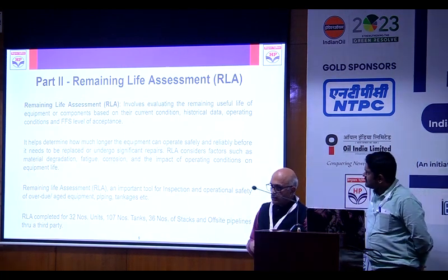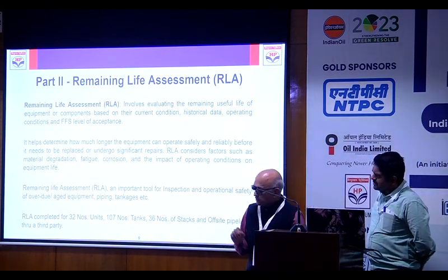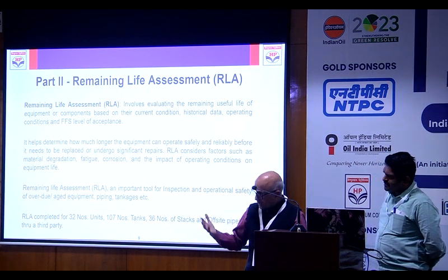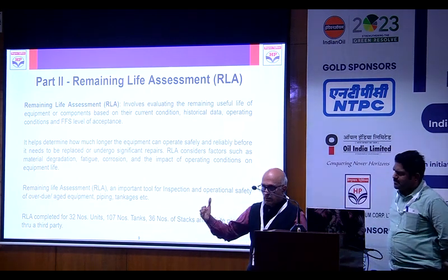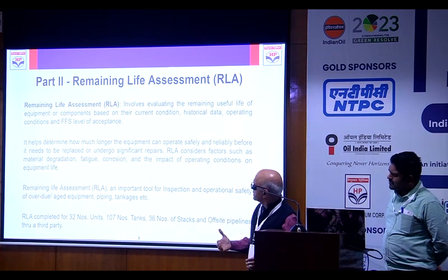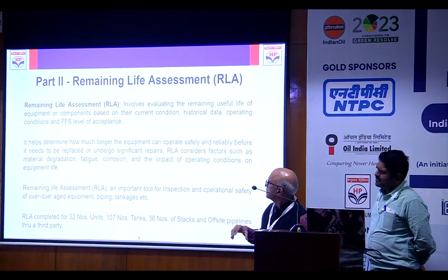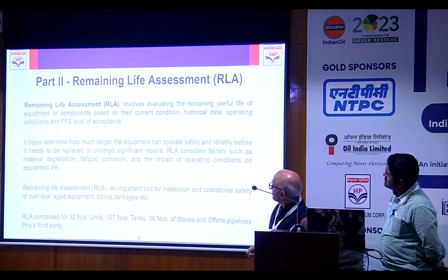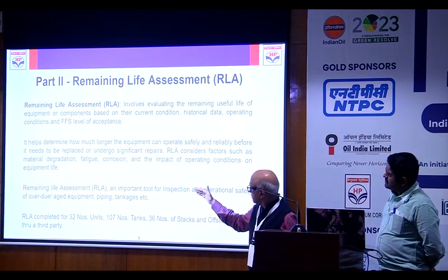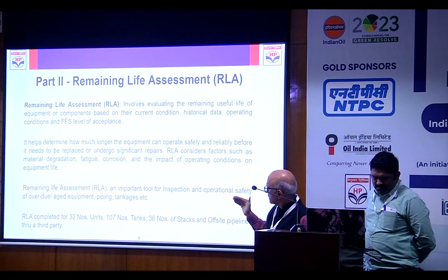Another case we carried out was a creep damage case. There also we calculated and it came out as a replace case. So we increased our monitoring and are making efforts to replace them. This is how we use FFS for our integrity management. Now remaining life, based on material degradation factors, all these things we consider.